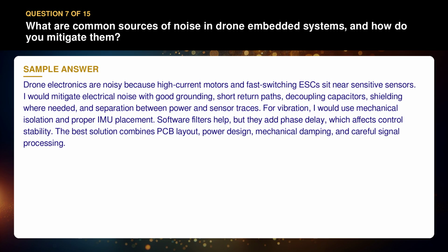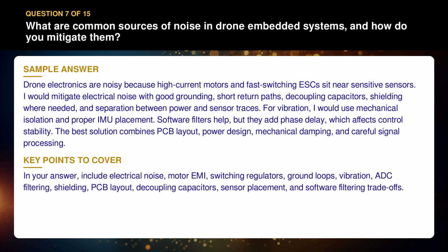Software filters help, but they add phase delay, which affects control stability. The best solution combines PCB layout, power design, mechanical damping, and careful signal processing. In your answer, include electrical noise, motor EMI, switching regulators, ground loops, vibration, ADC filtering, shielding, PCB layout, decoupling capacitors, sensor placement, and software filtering trade-offs.